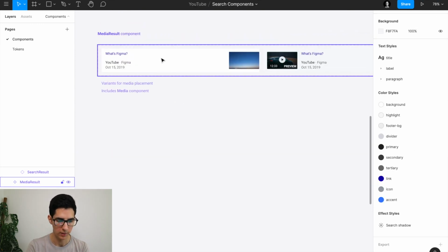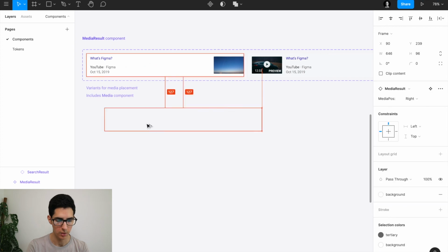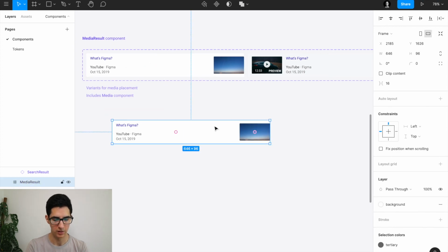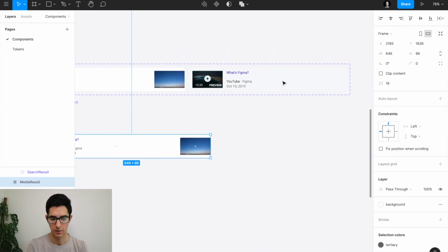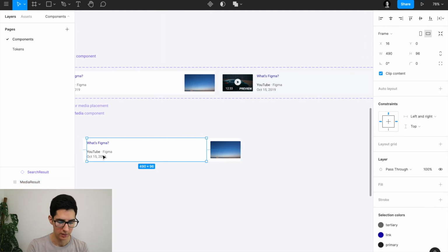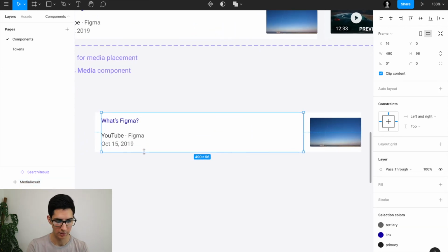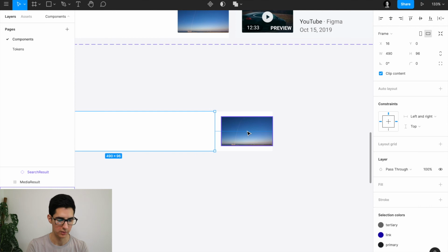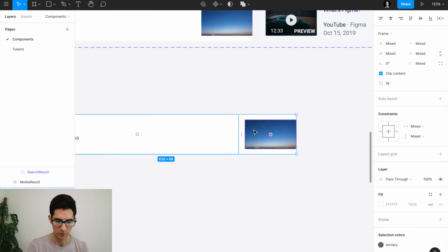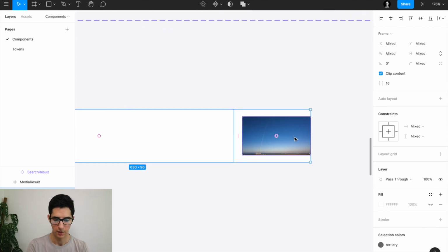And if you want to change this from left to right, it's quite easy. All you do is select this layer and then shift this layer, and you can see there are these two dots, which are helpful in order to readjust things easily on Figma.